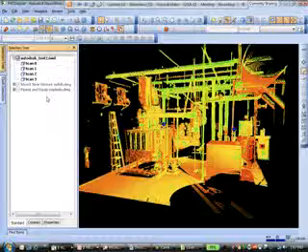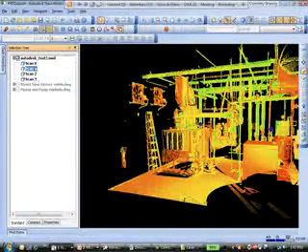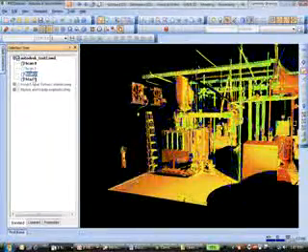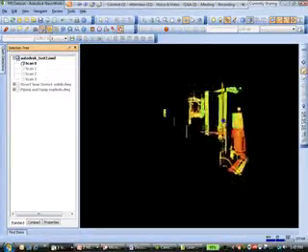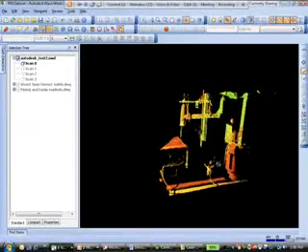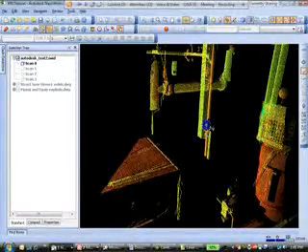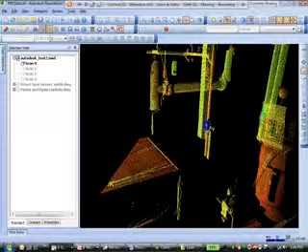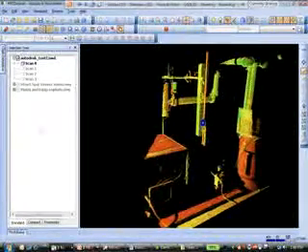So yeah, most scanners will have a software that comes with it that allows you to stitch together these different scans. In this particular case, this model was built up from 4 separate scans, and I'll turn these off just so that we can see. So scan 0, for example, was the initial scan that was done on here, and it's just a small sliver. You can see it doesn't really encompass a lot, but it gets very detailed in this small area. And you'll notice a lot of these have these little blue dots. So these are the reference planes that were set up when they were scanned. That allows them to specify the height. And then that way when they stitch them together, they have the orientation, they have the GIS information for these.